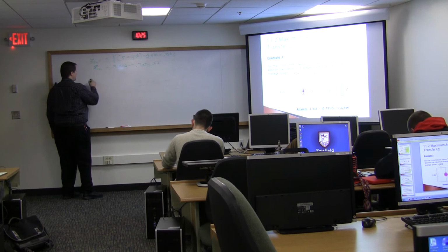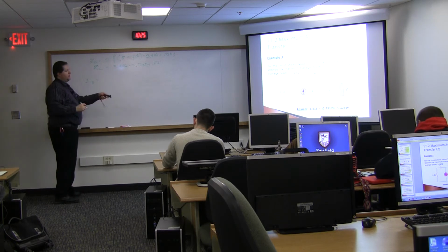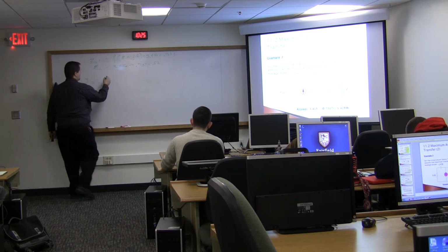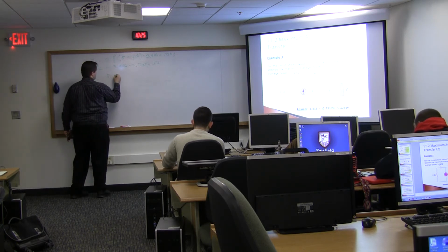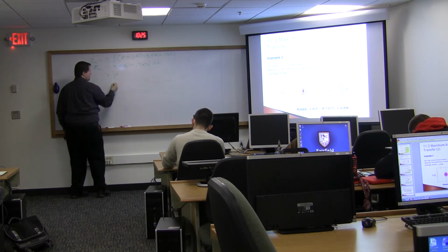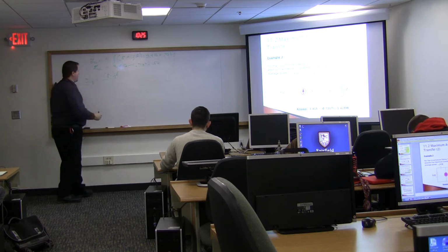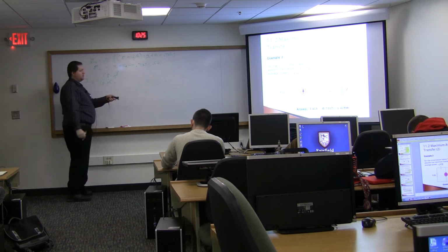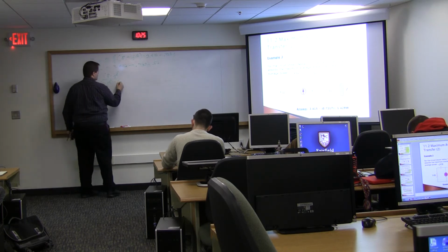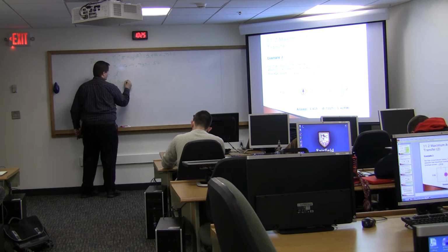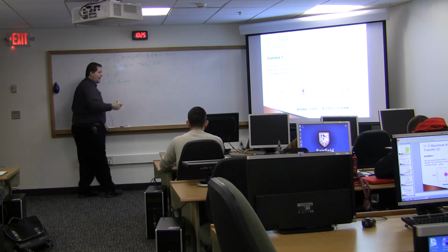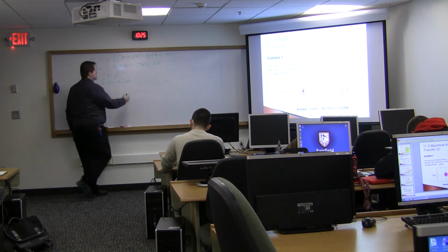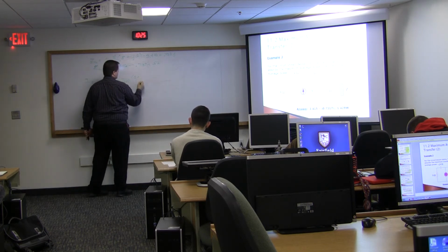So I in the right is going to be equal to 8 minus j4 divided by 8 minus j4 plus 5 plus j10, times my input current, 2.